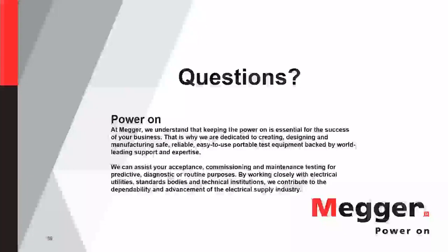Generally if you have 245 kV circuit breakers and below, they usually have one operating mechanism that operates all 3 phases. So you really want to use one transducer per operating mechanism. So if it's gang operated, you just want that single, we call it single phase, but really it should be called a gang operated kit.